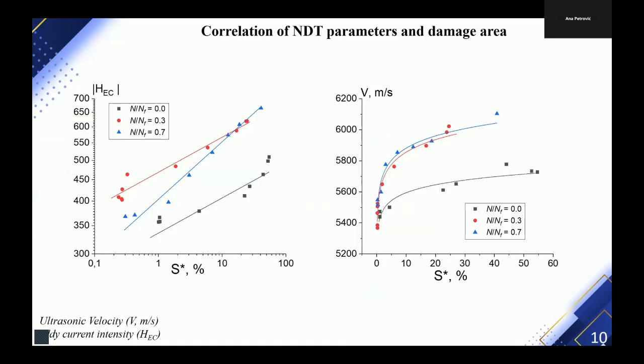With damage assessment, we try to find a correlation of non-destructive testing parameters and damage area, relative damage area. Here you can see the results of eddy current and ultrasonic velocity of our material during tests. And we find that every curve obeys a power law relationship.